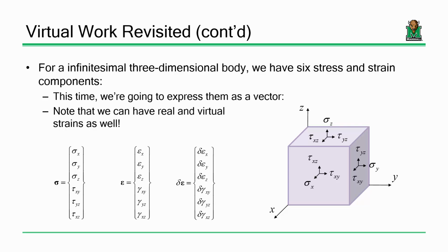Well, my point is that in general, for any physical body in 3 dimensions, there are 6 potential stresses and 6 potential resulting strains, right? Okay? I propose to you, you have 3 potential normal stresses and 3 potential shear stresses, and 3 potential normal strains and 3 potential shear strains. Now, this point that I'm making right here is a little subtle, and it's actually a little different than what I was talking about before.